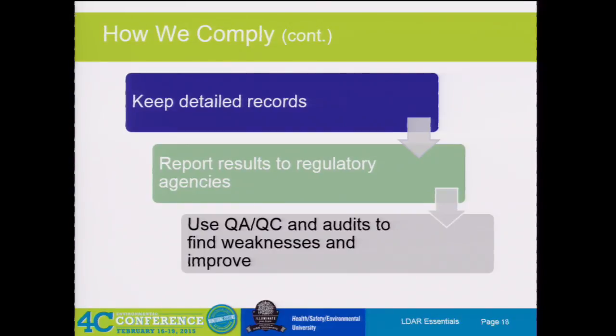Most of y'all have databases. I only know a few sites that are extremely small that manage it in Excel or something along those lines, and I'm talking very small. So you guys are very easily covered with your LeakDAS and Guideware database. Make sure though when you're starting to look into those databases that sometimes they can mess up, or at least my computer always breaks, it seems. So you want to make sure that you have something in play to do little QA/QC audits directly into your database to make sure that no ghost things have happened or magic voodoo where some key touches something and whatnot.